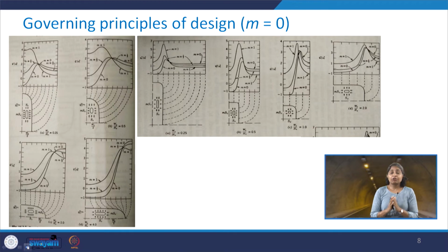What I said was the extension of the horizontal axis. So I extend this horizontal axis from the end, and you see that near this region only you are getting the maximum value. You take any figure, and approximately in that zone you will have the maximum value, and you see that as you move away from this horizontal boundary, the stress concentration factor is reducing. You can see that it is almost true in all these situations, for any shape of the opening having any value of W naught upon H naught.